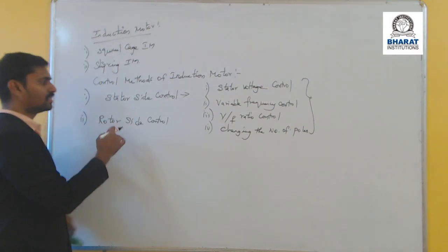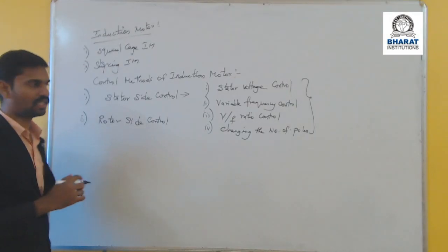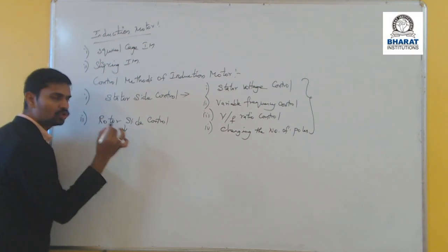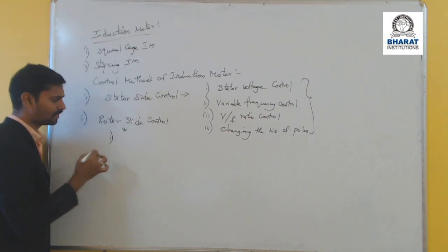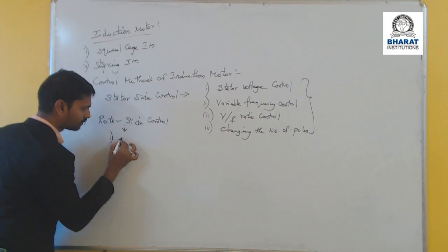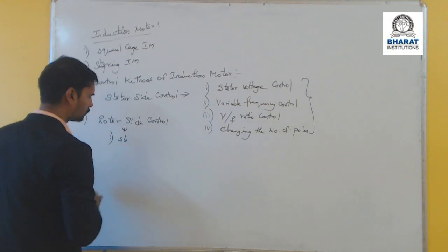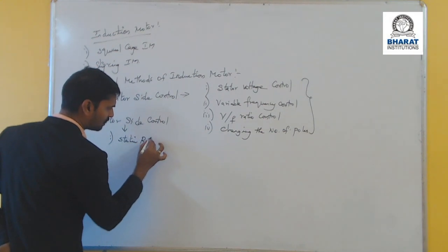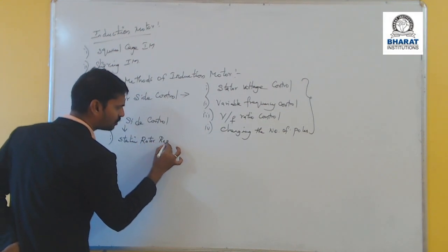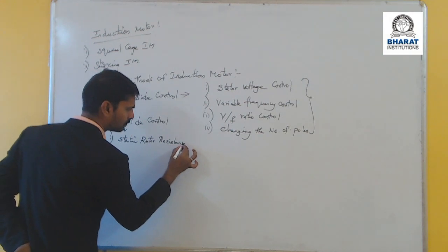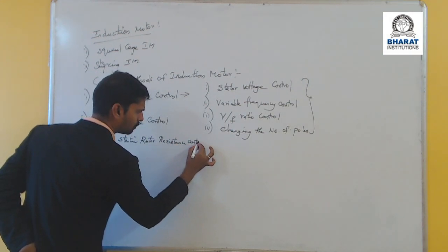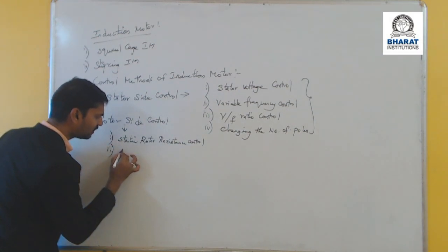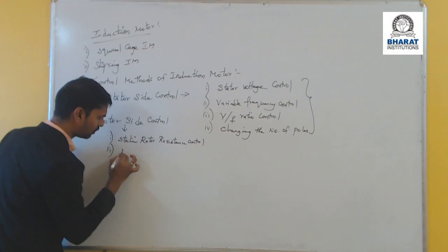So next methodology is rotor side control methodology. So again, the rotor side control methodology can be classified into two types. The first type is static rotor resistance control. The second type is injecting the EMF into the rotor circuit.